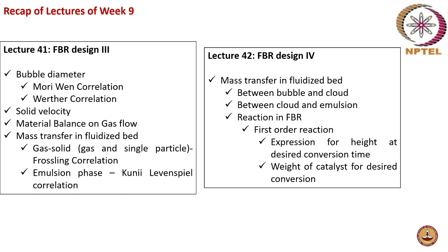You remember, right? In a fluidized bed reactor, there is a bubble formation, and this bubble will have a wake, where more solid particles are concentrated. This is in the bottom end, the rear end of the bubble. And then this is surrounded by a cloud phase, and then further there is an emulsion phase surrounding it, right? Do you remember that? Yes, ma'am. Did you go through last week's lecture? Yes, ma'am.